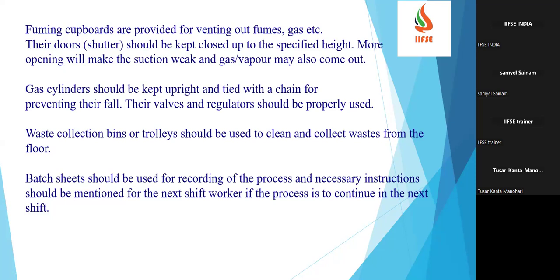So the waste collection is also a major concern, especially in chemical industries. We should not allow them to practice throwing all kinds of waste or collecting different kinds of waste in a single bin or one container, because we don't know which chemical will react with which chemical. Maybe a chemical may react with Z, but we don't have that information with us. We thought a chemical will not react with A, X or Y chemicals, but unfortunately it reacts violently with Z, which was recently added in my process. So the hazardous waste must be collected separately. We should have different waste bins. People should be well trained on the collection, identification, and handling.